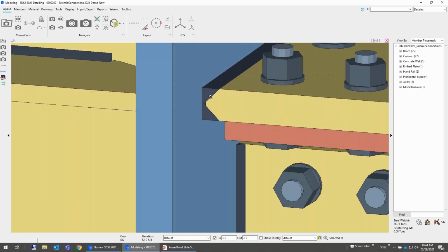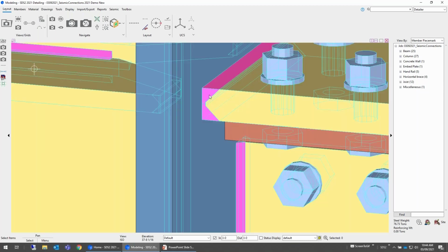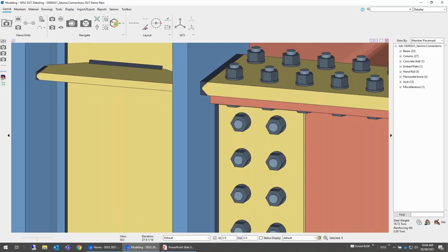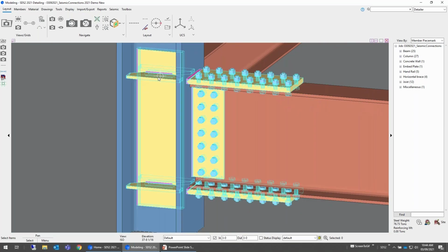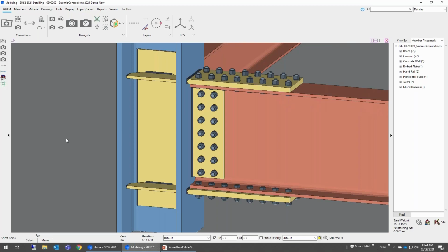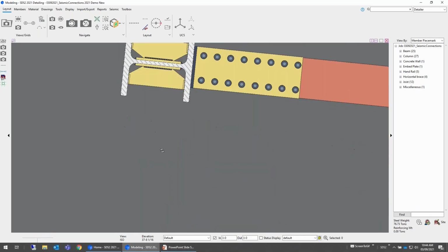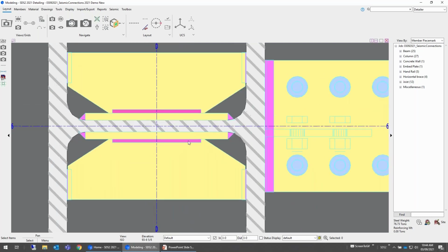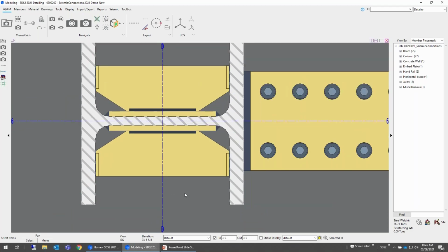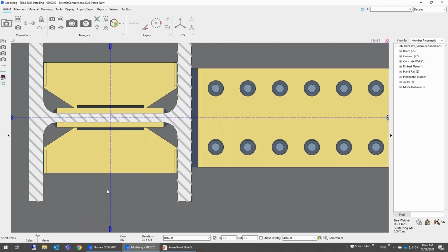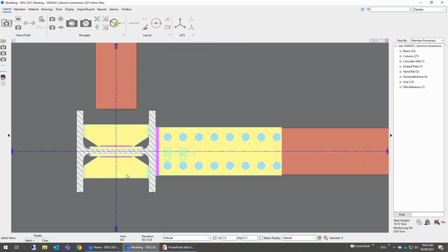You can see we have the CJP weld attaching to the column as was specified in the 358. There are some CJP welds on the stiffeners there also. These do have special detailing requirements, and they're mostly to do with the clearance around that K distance. So we're going to see some additional clearance there, and we're meeting those requirements.